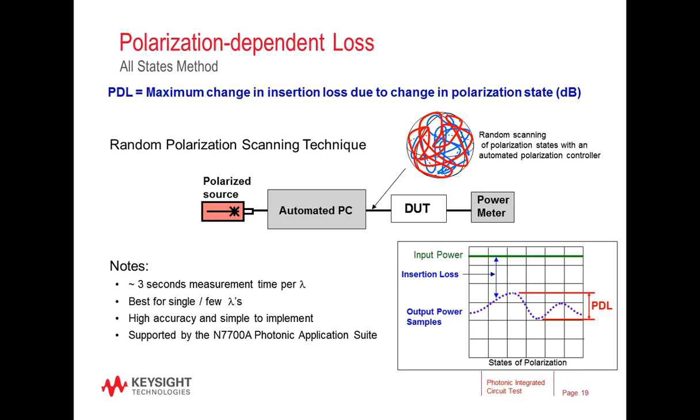Polarization-dependent loss describes the maximum change in insertion loss of a device over all states of polarization. It is a critical performance metric for PIC designs that aim for polarization-independent operation, or for PICs that have polarization-diverse operation. For single polarization PICs, it is also important, as the launched light can often have limited polarization extinction ratios, and thus two polarizations are actually launched when only one was intended.